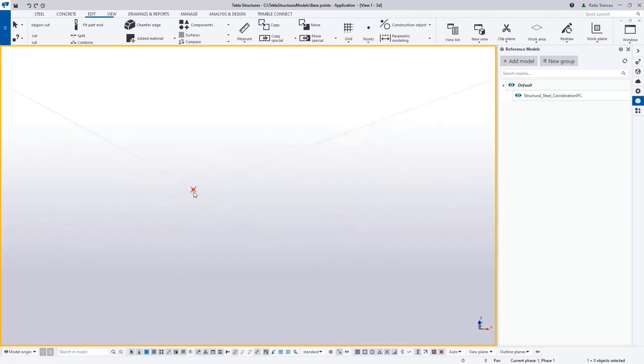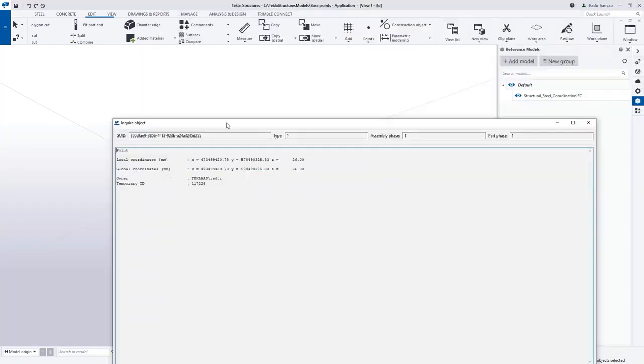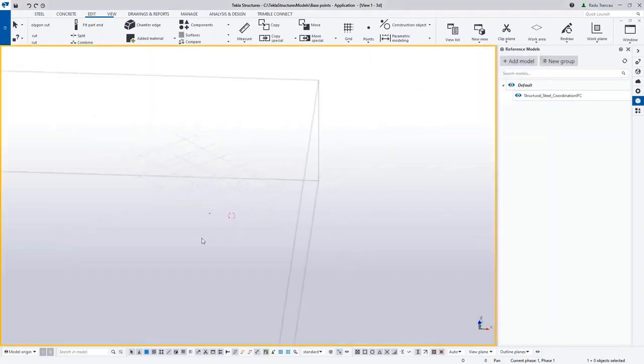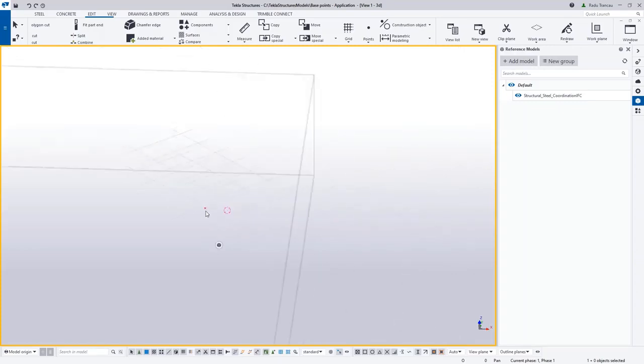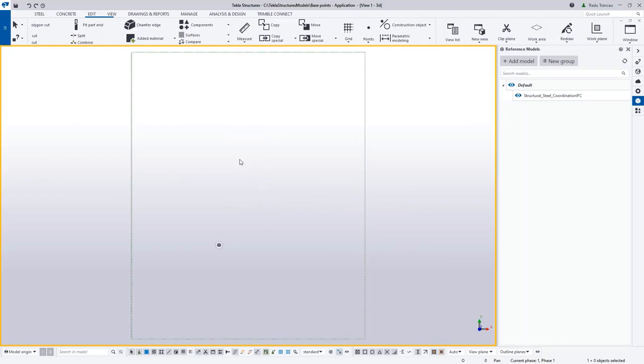Okay, so just to have a little bit of an awareness of how far this point is located from the origin, you will see it sits somewhere 473 kilometers on X and 578 kilometers on Y, and this is too much. Everything that exceeds probably 100 or 150 kilometers away, you will start to have serious conflicts in the output of the graphics. Okay, so let's fix this situation right now.